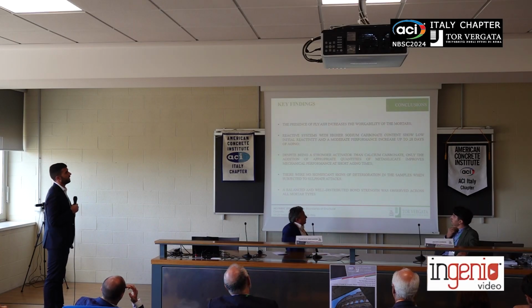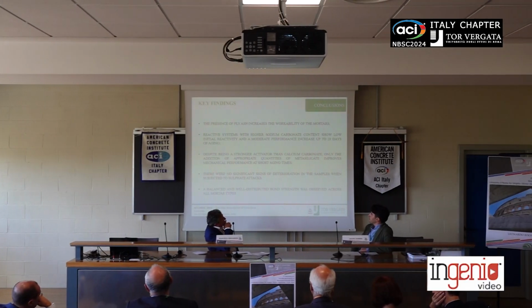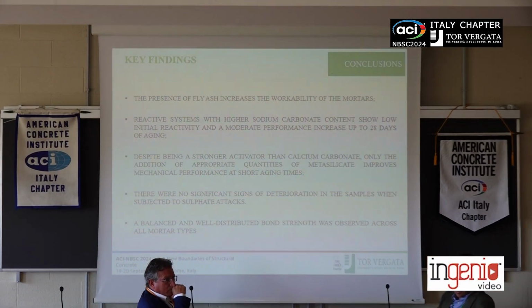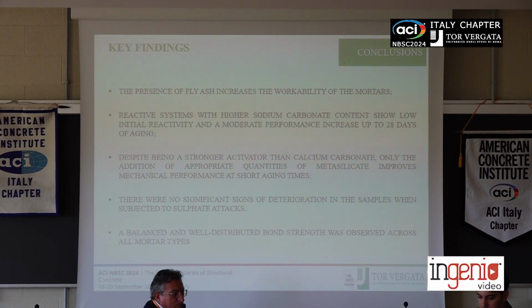In conclusion, what we can see from the results that we just observed is that the presence of fly ash increases the workability of the mortar. The reactive system with higher sodium carbonate content shows low initial reactivity and moderate performance up to 20 days of aging. Despite being a stronger activator than calcium carbonate, only the addition of an appropriate quantity of metasilicate improves the mechanical performance, especially at short aging times. There were no significant signs of deterioration regarding the behavior under sulfate attack, and also the bond between the mortar and the substrate seems to highlight a good potential for FRCM application.